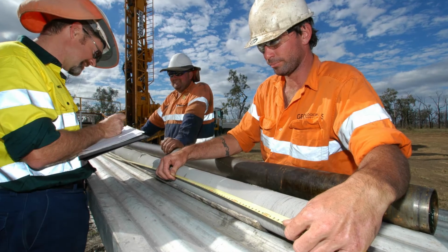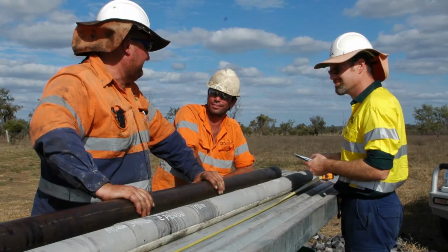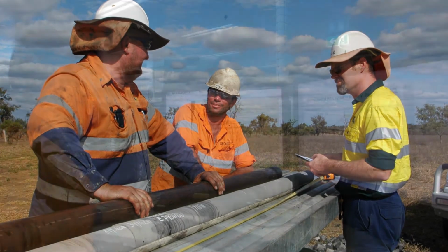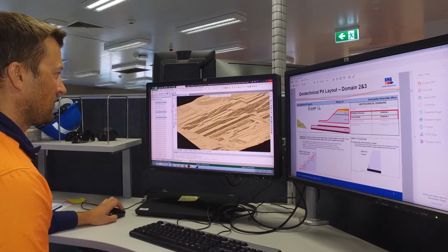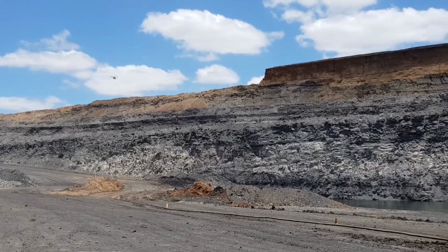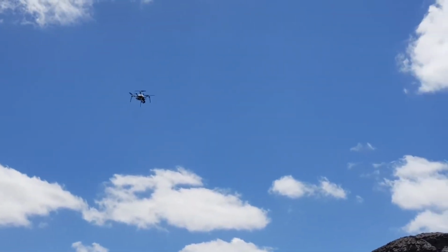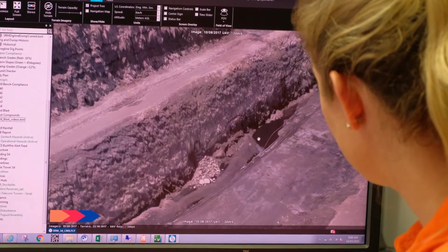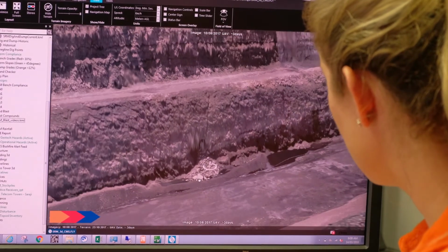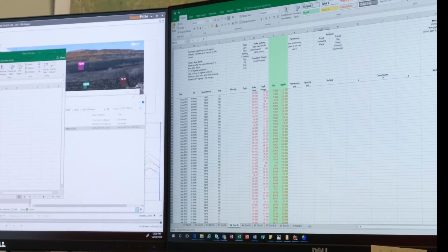This type of structural data is acquired from exploration logging of core, geophysical logging using acoustic televiewer tools, 2D and 3D seismic programs to identify large-scale structure, and high wall mapping using laser scanner, drone or photogrammetry acquired data to quantify joint sets, spacing, orientation and persistence. All data acquired from exploration and structural mapping should be kept in a defect database.